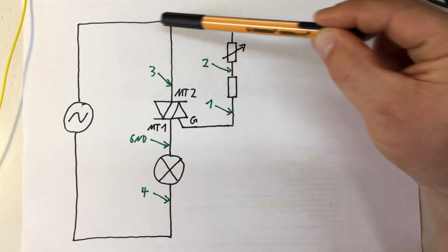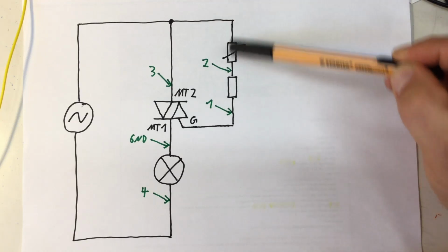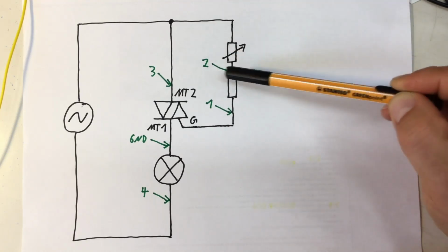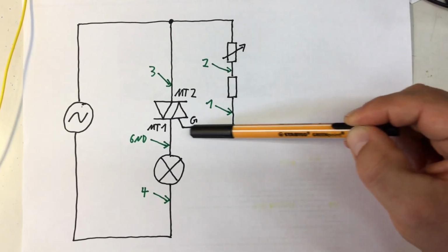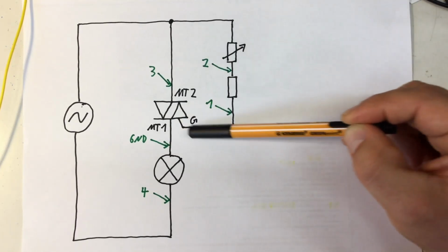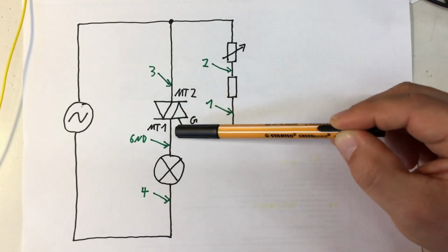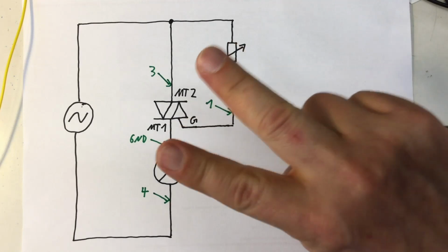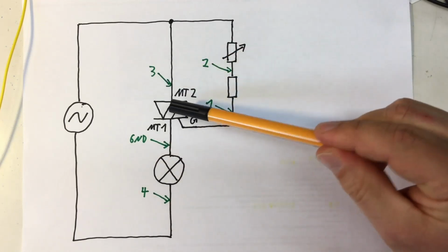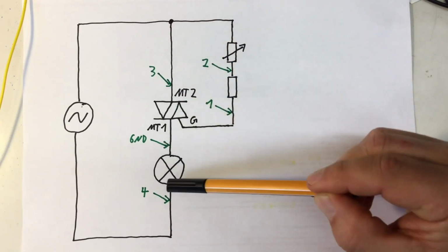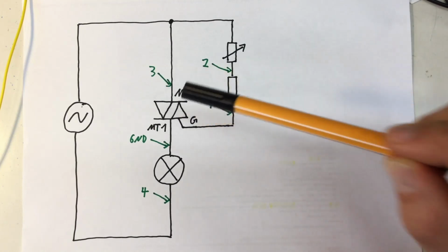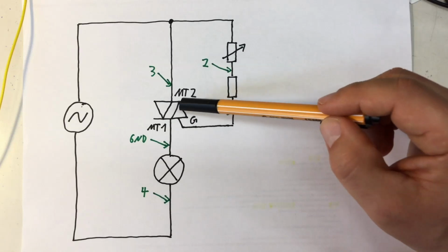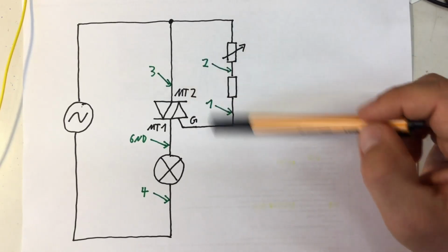And that means I no longer have a voltage drop across the resistors, maybe a volt or so, and the gate current is no longer supplied. So this kind of circuit works really in two phases. It's off, gate current is supplied, TRIAC is on, no longer any gate current is supplied, or very little.